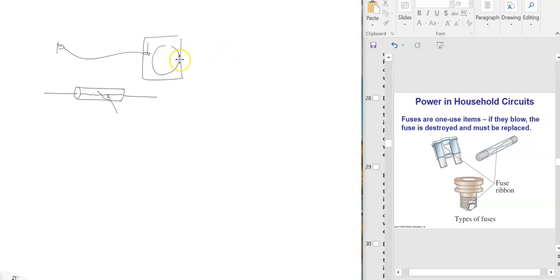If there's a leak or something, let's say somebody comes in, tries to operate this, there is a leak in the circuitry, and so there's electricity present on the casing. You go and touch this, if your hands are wet and if your feet are also wet, which can happen when you're washing clothes and all that, you are creating a secondary path through you to the ground. So the system is going to draw too much current.